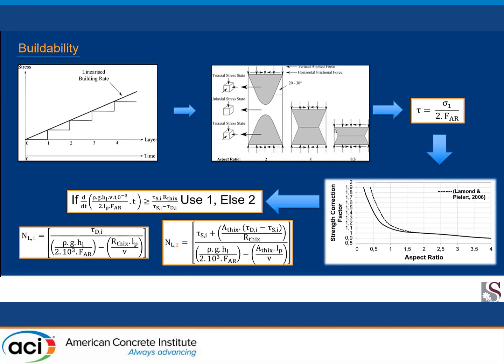And you can see that actually what happens is that the top and the bottom coincide, and then you have a very large area that's in a triaxial stress state. So what we found is that, relative to the force, it increases the loading capacity, the bearing capacity, that this filament layer can bear. So what we did, we essentially just normalized the strength at an aspect ratio of 2 using the Tresca failure criterion, and then as you go lower with the aspect ratio, it increases relative to that.